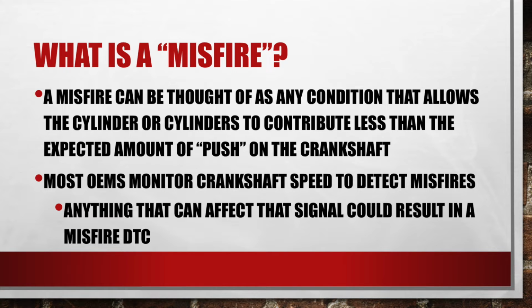In my mind, a misfire is any condition that allows the cylinder or cylinders to contribute less than the expected amount of push to the crankshaft. Now, what do I mean by that? If all 8 cylinders are running the way they should, they're all contributing an equal amount of power, aren't they? If a condition occurs that allows one or more cylinders to contribute even a little less than it should, then it's going to apply a little less push on that crankshaft, isn't it? And the crankshaft is actually going to momentarily slow down.